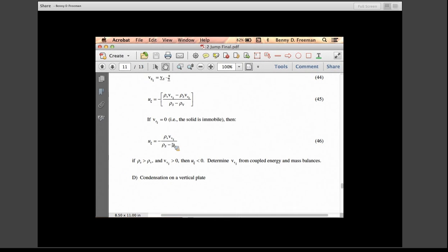When we look back at that problem, what we will see is that the fact that the interface moves very slowly relative to the gas phase velocity allows us to make the assumption that the net flux or velocity of the nitrogen, the non-evaporating species in the gas phase in the Stefan tube problem, is orders of magnitude less than that of the liquid that's evaporated.